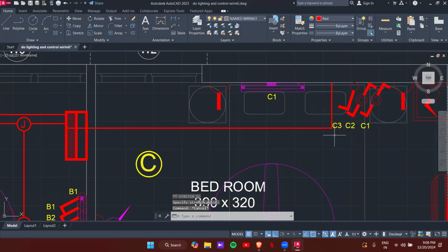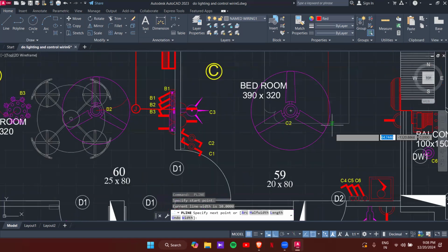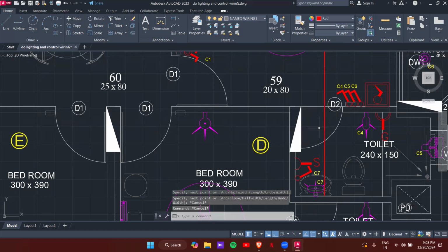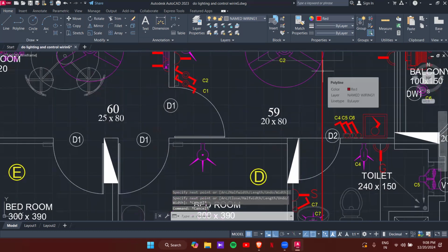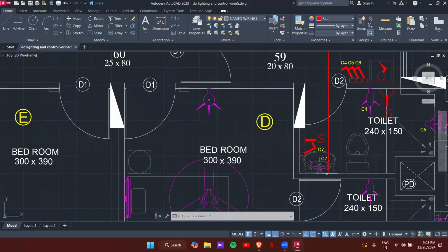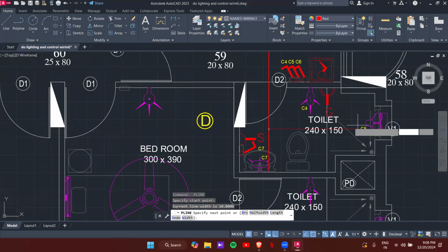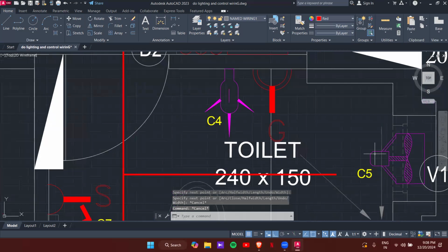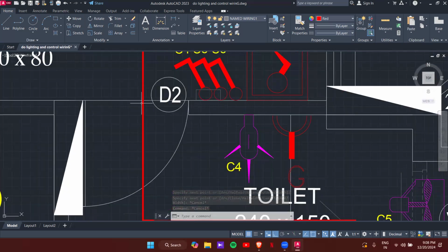Okay, and it here. Then from here, I'll draw one branch, and then I will directly go into this space. Okay. So you can notice one thing: the conduit is actually passing through this space here over this spot. That means these connections will be also taken care of. And I will end it over this part. That means the fixtures over this wall will be also connected. Okay. Finally, I will end it here so that the exhaust fan connection will go through here.